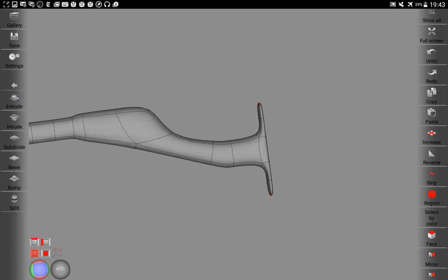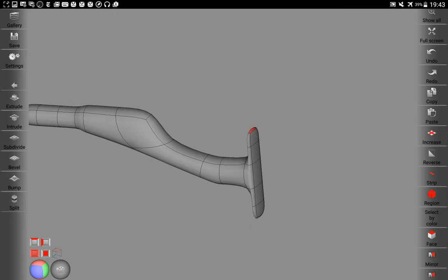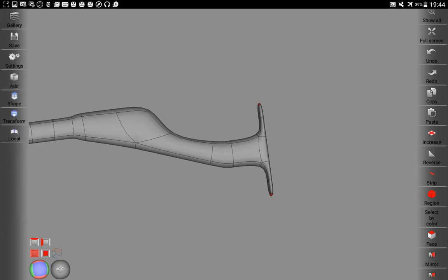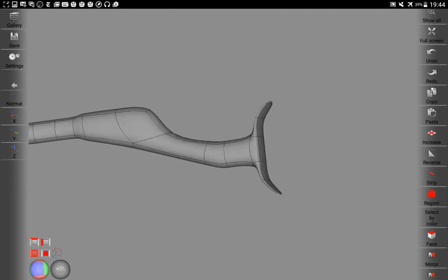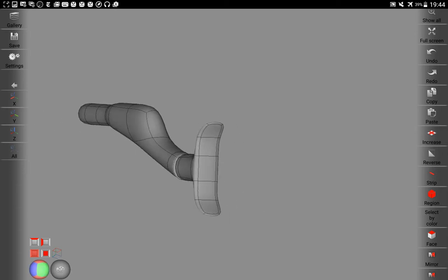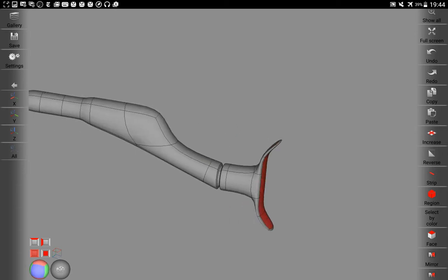So you see, that's a bit of the workflow you will have, and you can have like 1 and 2 of these things here again, and you just transform move them on the y-axis, and you get something like this. And this here you grab and you shape, subdivide it, subdivide, transform, scale it on all edges. So this is actually the connector, and then we give it here like a little bit more detail.